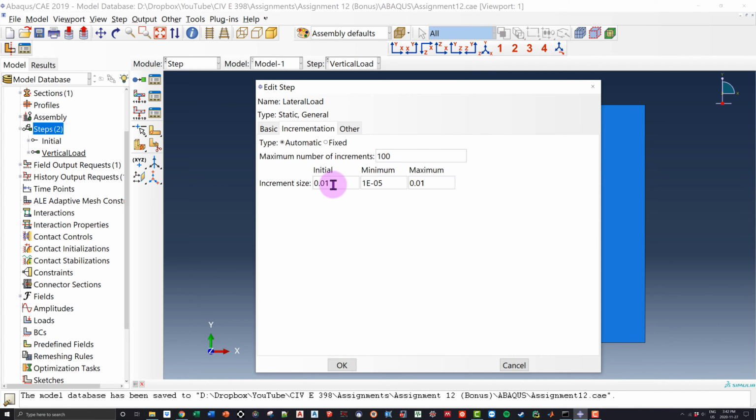Now what's going to happen is instead of going right from 0 millimeters to 3 millimeters, it's going to apply 1% of 3 millimeters all the way until it reaches 3 millimeters. And just in case there is some unsuccessful incrementation, I'm just going to change this to 1,000, but you guys shouldn't actually need to worry about that. So just put it as 1,000. I don't think there's going to be any unsuccessful incrementations, all right?